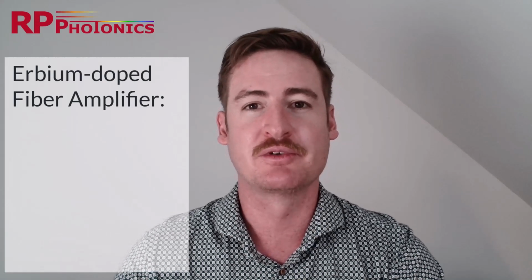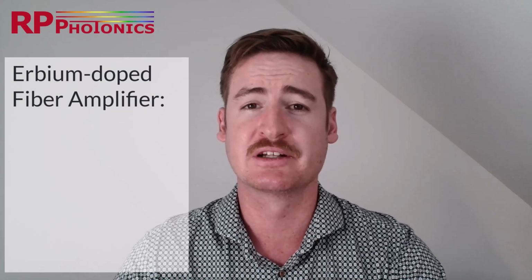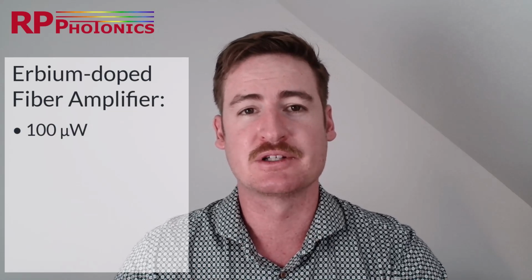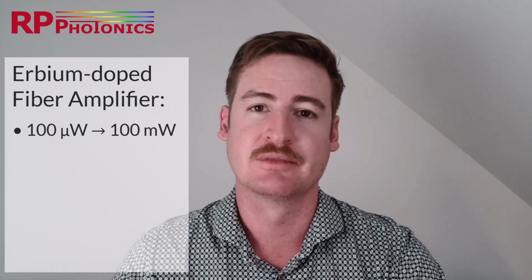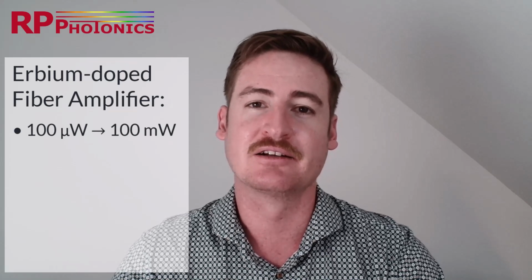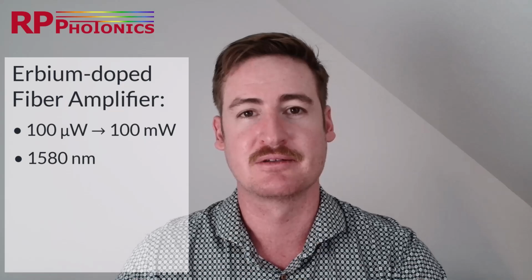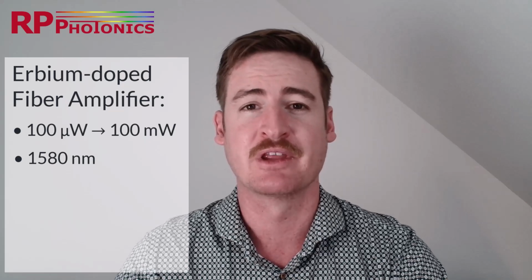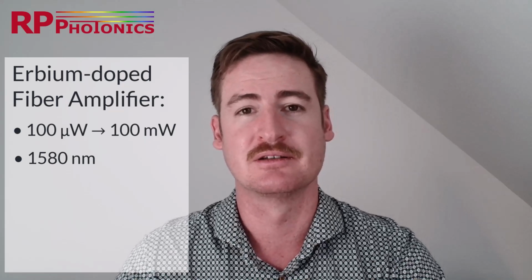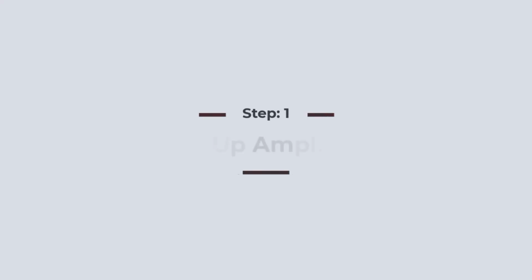In this video, the aim is to design an erbium-doped fiber amplifier to boost the signal from around 100 microwatts to at least 100 milliwatts. The challenge is that the signal is at 1580 nanometers. This is far from the gain maximum, around 1530 nanometers. Let's see what can be done.